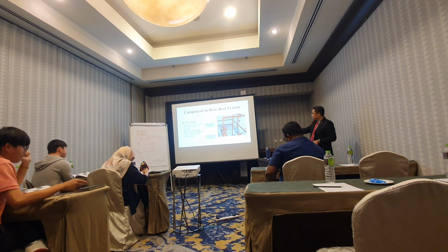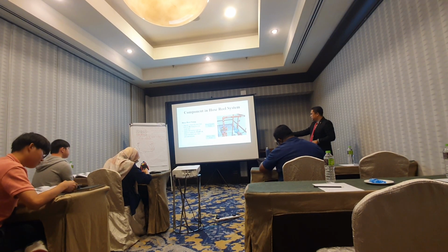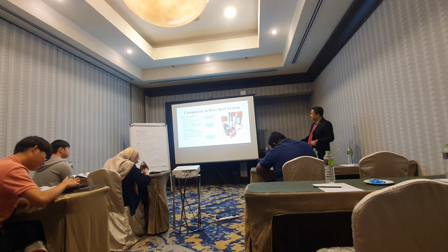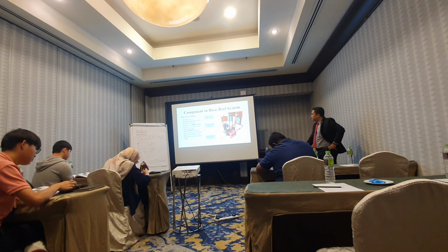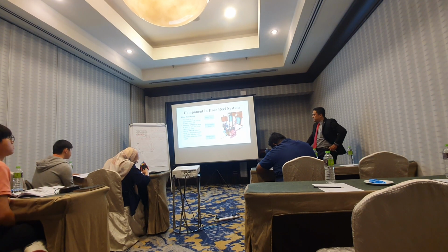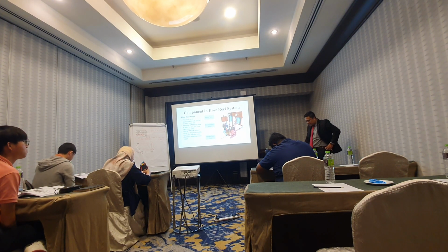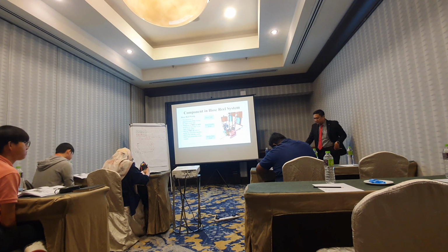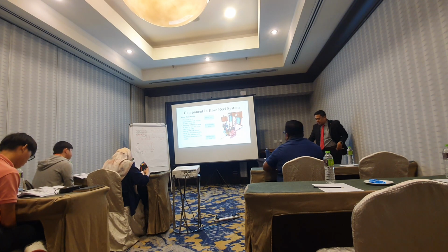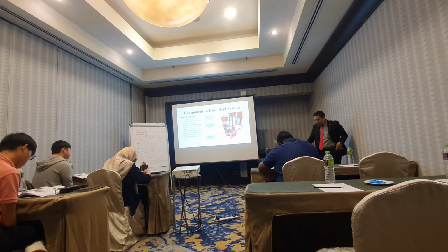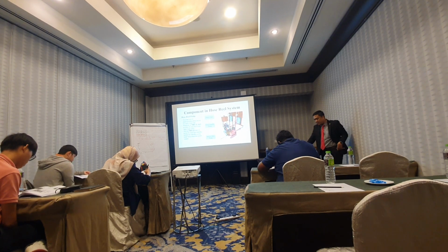So for the pump, you need to check the distance. The other requirements for the pump: it must provide a jet of approximately 6 meters throw for each hose reel, with a pressure of 2 bars at entry of any 4 hose reels. It must have 2 sets of pumps, duty and standby, where the standby pump shall have essential power supply.